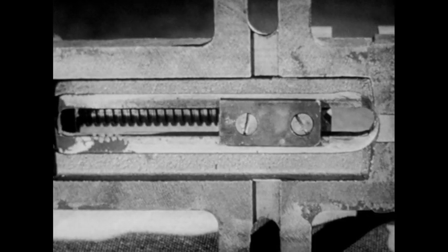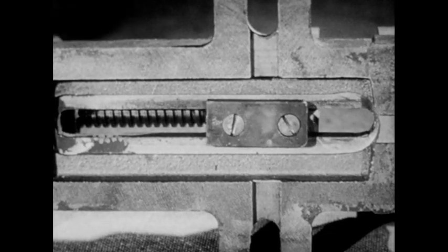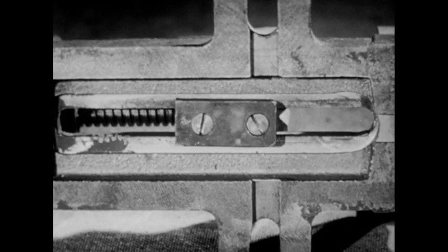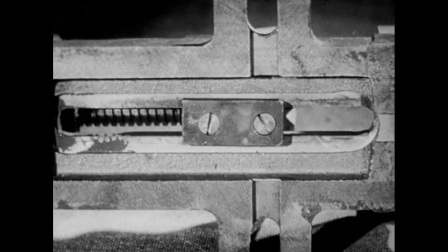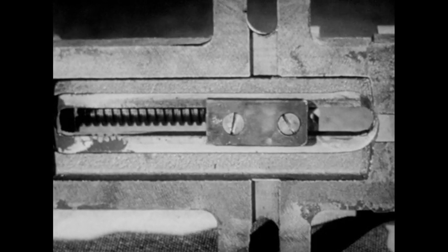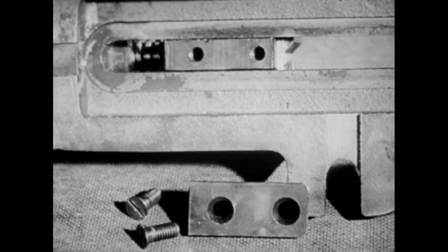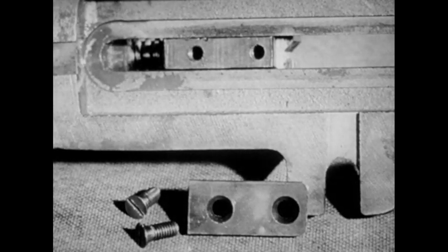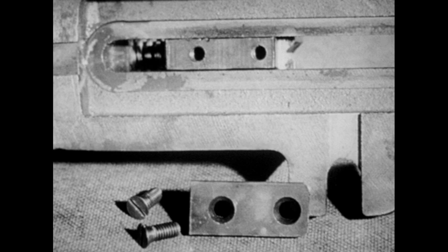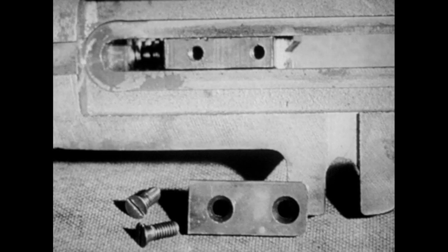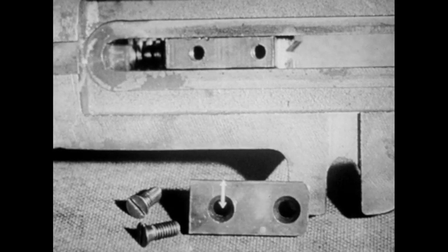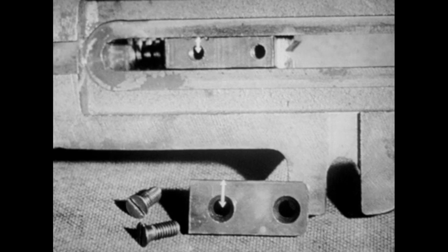The plate must be aligned with the movable jaw tongue so that it does not hit the sides of the milled groove. Therefore, the screw holes must be centered in the movable jaw and in the plate. Give the distances from the center line of the screw holes to the edge of the plate and to the edge of the tongue on the movable jaw.